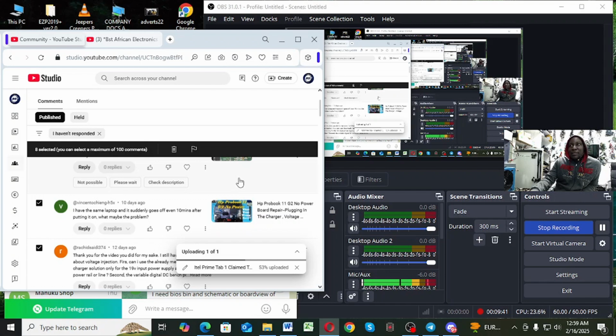Based on experience, I'll start to check the cooling system of that particular motherboard. Try to check if the cooling system is working properly, like the fans are spinning properly and the machine is not overheating. Try to change the thermal paste. That's where you can start.